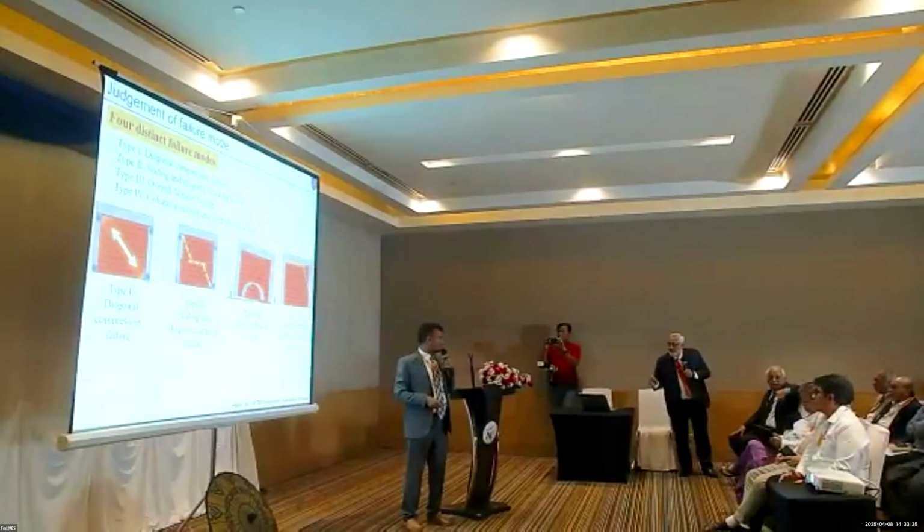But when it comes to designing the buildings, and if it is a framed structure, we don't normally take the masonry into account because masonry is brittle, and at some stage it can crush. And that's the mode of failure that is spoken about. So these were the two things. But this is for an existing building, where the masonry is already there, and we can make use of that particular non-structural element. I hope I was able to answer.